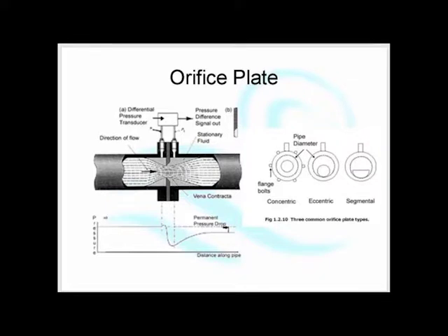Now we're starting to look at flow meters. When we look at flow meters, I need to ask a few questions each time. When I ask the questions, you'll see there's a little green tick and a red cross at the top of your screens. When I ask these questions, if you can give me a tick or a cross if you think it'll work. There are 3 types of orifice plates. With an orifice plate flow meter, it's basically a metal plate with a hole in it, and the fluid goes through it, and we measure the pressure either side.